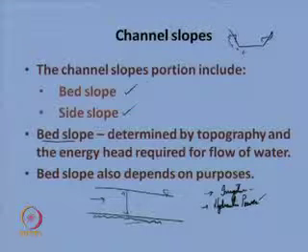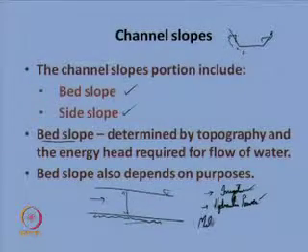If it has to be at higher elevation, what do you mean by that? Then whichever channel is feeding these channels needs to be at a higher elevation. So, in those channels the bed elevation also needs to be kept at a higher level, so that you will be able to feed water properly for the irrigation projects, hydraulic power projects and all. In most of the cases you use mild slopes. In such situations, mild slope channels or negligible slope channels are used.